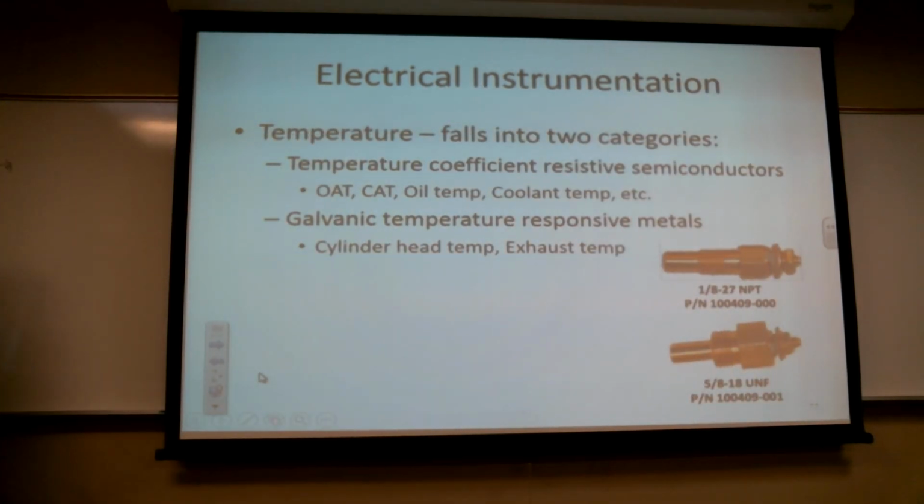Now, if I've got something like exhaust gas temp, so I'm at 1800 degrees, 1900 degrees, man, this thing's going to work really well. In fact, the bigger problem with it is, take a couple pieces of metal and stick them in hot gases that are burning at 2000 degrees. They might not last very long. I'm going to have to shield this thing very carefully and put it in a nice package so that it doesn't get eroded away.